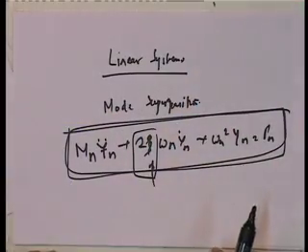All of these discussions come into the picture only when you ultimately have to look at nonlinear response, and you want to ensure that in the linear domain, the two methods give you the same result. That's when all of this about Caughey, Rayleigh, mass, stiffness proportional damping becomes relevant. If you are only dealing with a linear system, there is no need whatsoever of looking at what kind of damping. You just assume it in this particular case. Do you understand that? Okay.